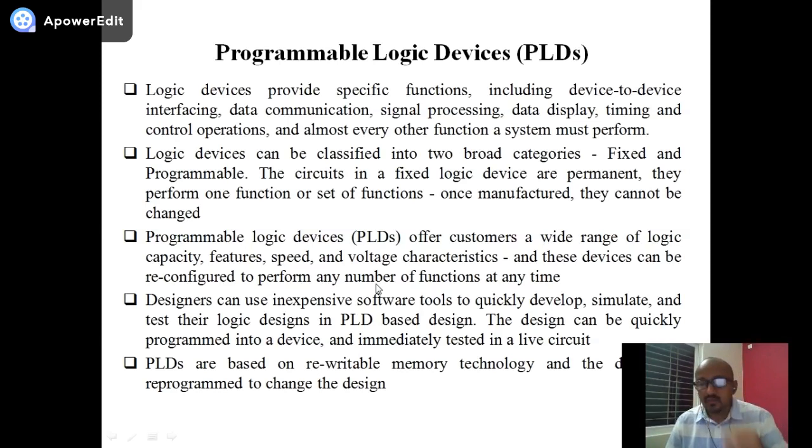For example, suppose you want to fabricate an adder IC. You write a program in Verilog, dump it on an FPGA, and then the prototype is ready, and you test it. If the tested code or design works according to your requirement or the function assigned to you to design, then it is sent to the fab for fabrication.